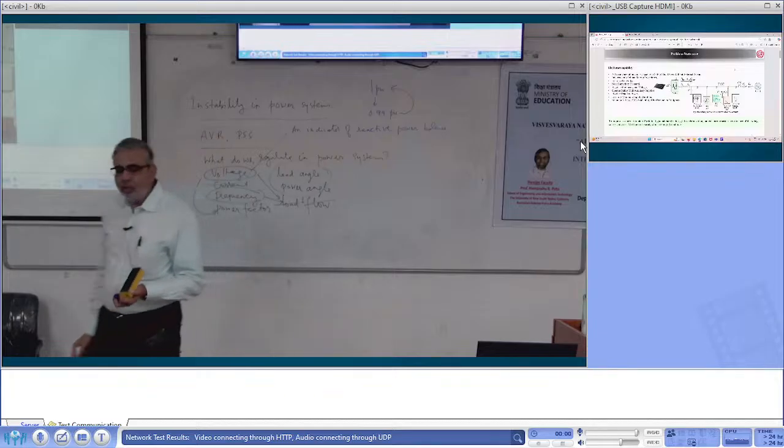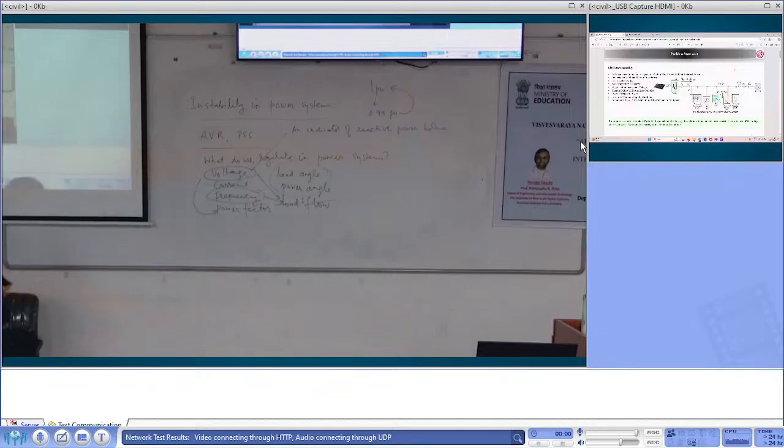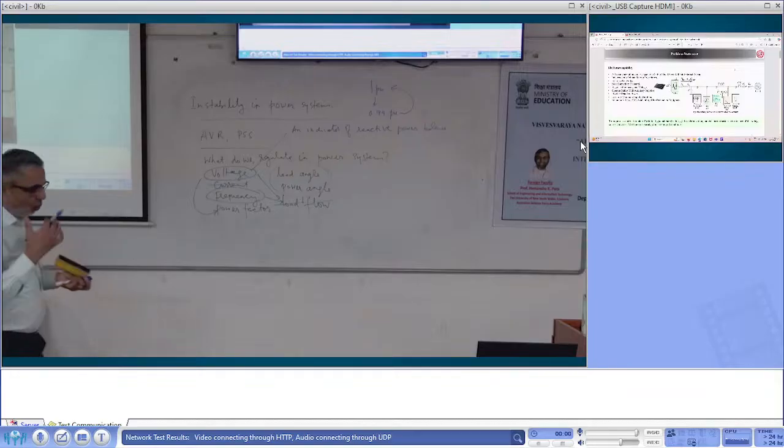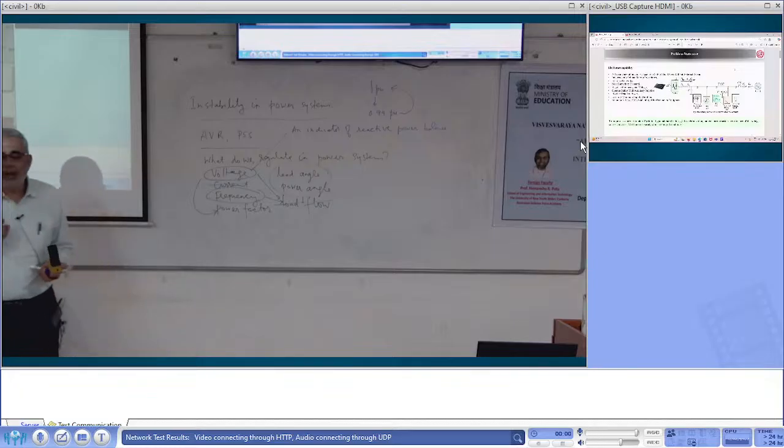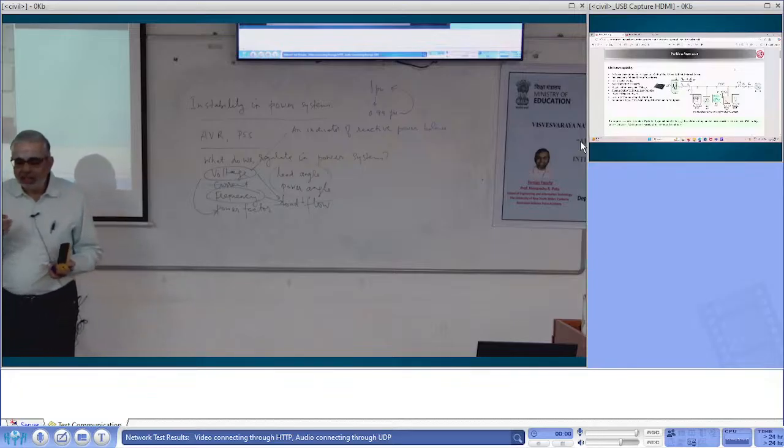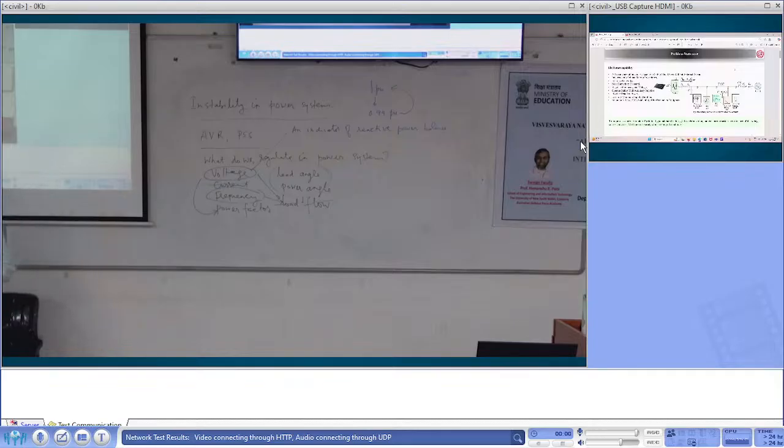They go back to 1 using AVR, and that AVR going up means that the generator is generating more reactive power. Right? And then the balance is there so that you know you are doing the right thing. So suddenly when you are at 0.9897 and if you don't make a correction, then suddenly the change might be too large for you to go back to 1. Okay, you might have voltage instability. So you keep correcting. So voltage is not such a big crime.